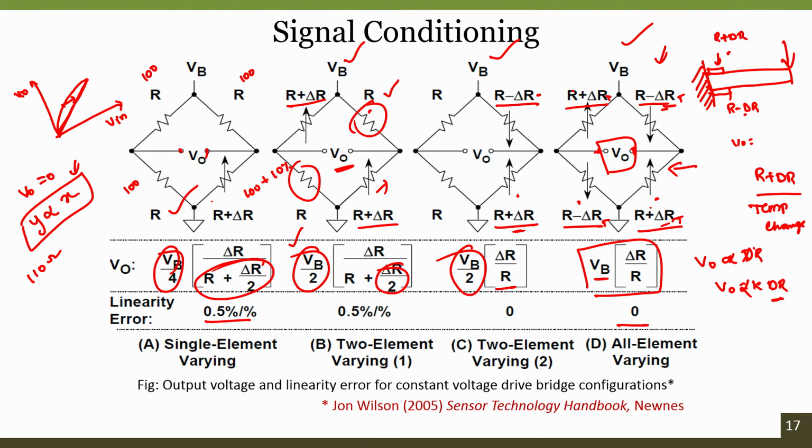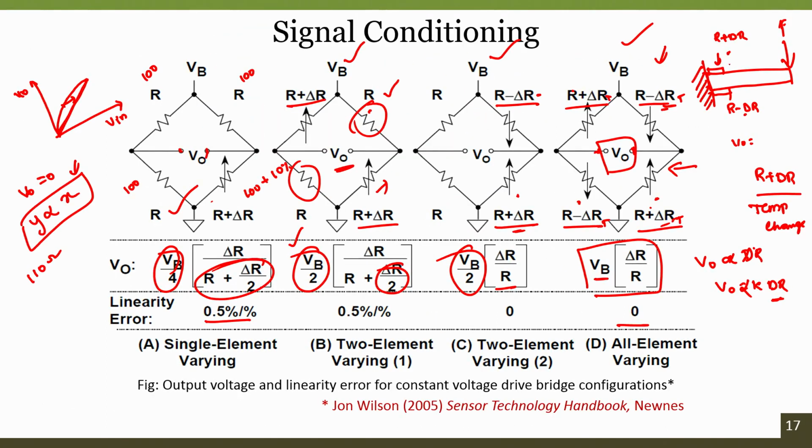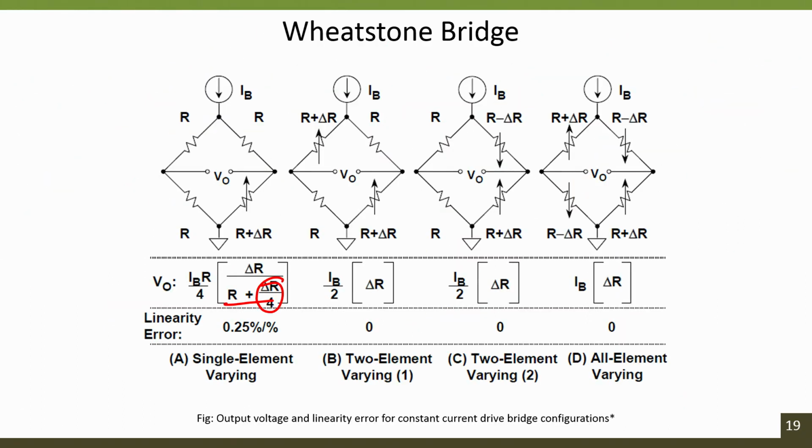At the same time, if there is any physical measurement change when the force is applied, the output voltage will be linear. This is how the 4 element varying bridge utilizing the Wheatstone bridge configuration works. Of course, in all cases you cannot get all 4 combinations of resistance. If we get them, we can introduce them, but what if we do not get all combinations of resistors here, say one with a PTC and the other with an NTC? Then we have to optimize our design in a similar fashion.